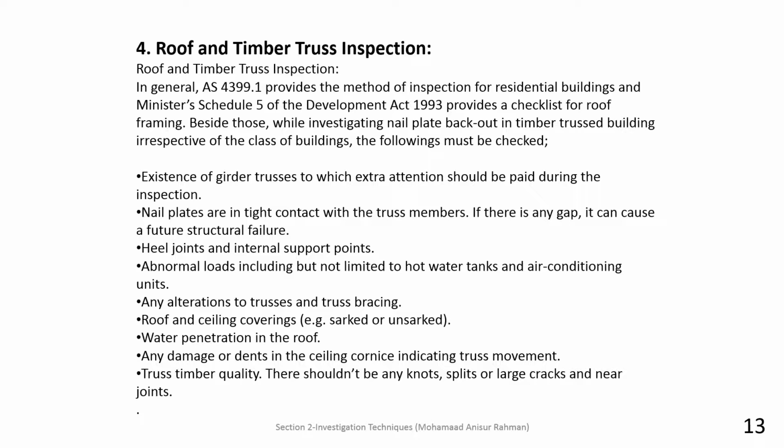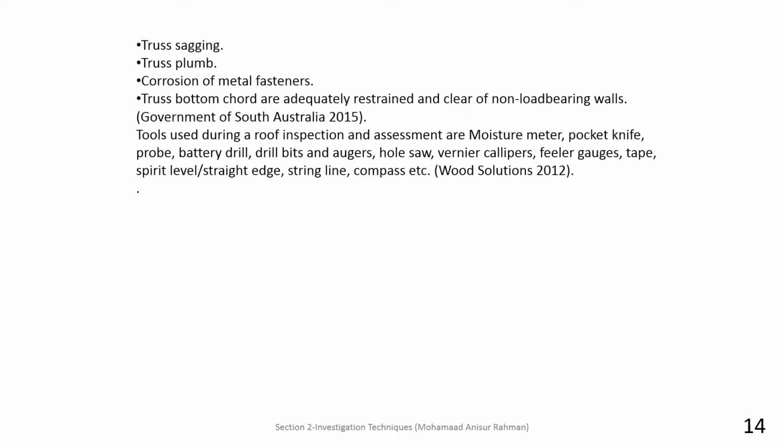Truss timber quality should be checked. There shouldn't be any knots, splits or large cracks near the joints. There shouldn't be any truss sagging and corrosion of metal fasteners. Truss bottom chord must be adequately restrained and clear of non-load bearing walls.